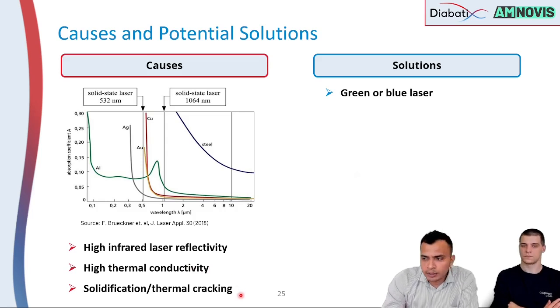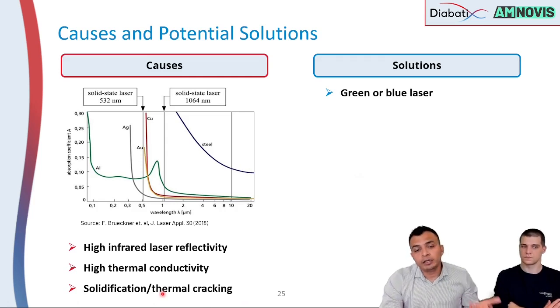In my experience, this is typically due to impurities in the raw material, because the raw material was designed for conventional manufacturing, whereas in additive manufacturing those impurities cannot be removed during processing and they stay inside and create cracking. That's what I saw, but with recent knowledge in this area, this problem has also been eliminated quite a bit.